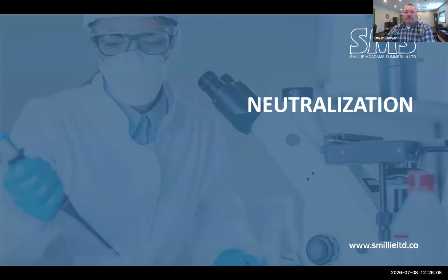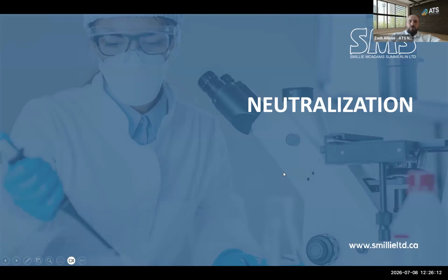Okay. And I'll prime it here. I'm sure you'll get into it, but it was asking more about when you have a drain in the chemical storage area, and a local plumbing inspector is saying that it can't be run to the regular sanitary. Correct. So understanding that perspective, that comes in where it needs to be neutralized before it gets into the sanitary. And I think you'll cover that.